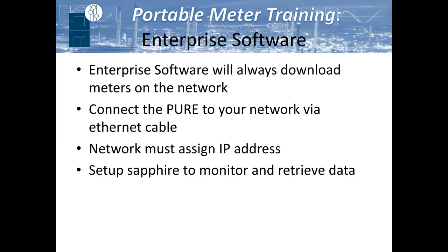So if you have Sapphire running and you have meters on your network, Sapphire is always going to be downloading the data in the background. So you don't ever have to worry about anything once everything's hooked up and connected correctly. You connect the Pure to your network via an Ethernet cable. Your network will then assign an IP address to the Pure, and then you set up Sapphire to monitor and retrieve data. Next slide, please.